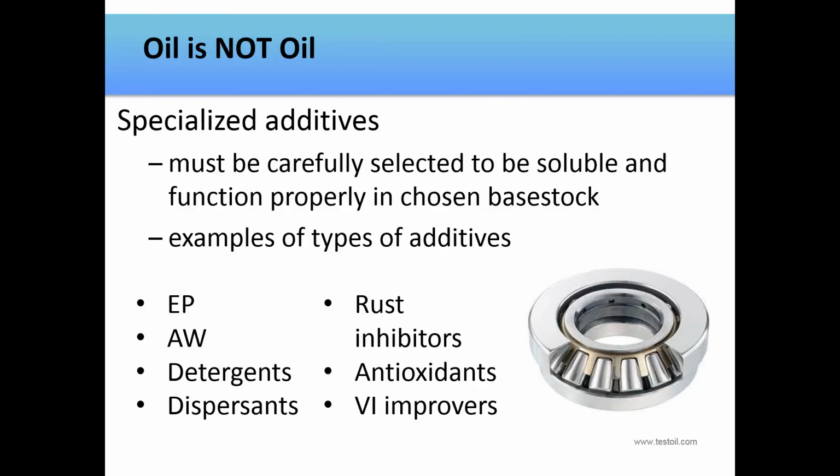And each type of additive is blended with a base oil to enhance that base stock's properties in accordance with the intended application. So lubricant manufacturers will spend time developing and tweaking specific lubricants even after they've been on the market. And since lubricants are carefully crafted to give the required performance characteristics for a machine type, it's really imperative that the compatibility of different lubricants is tested if a mixture is to be used in a machine.